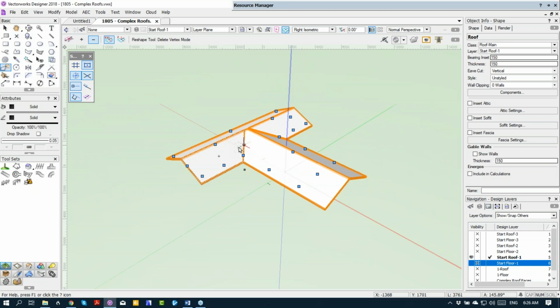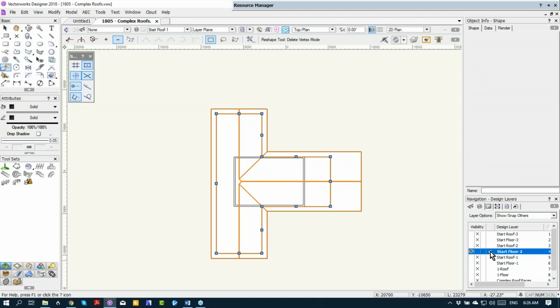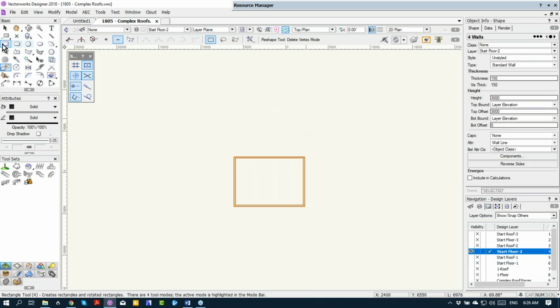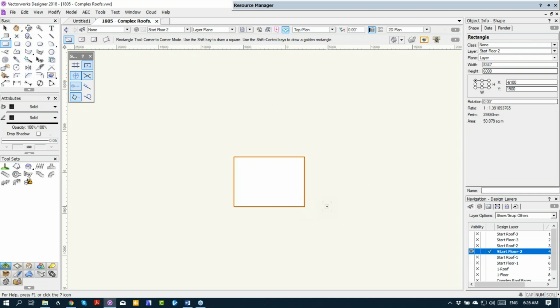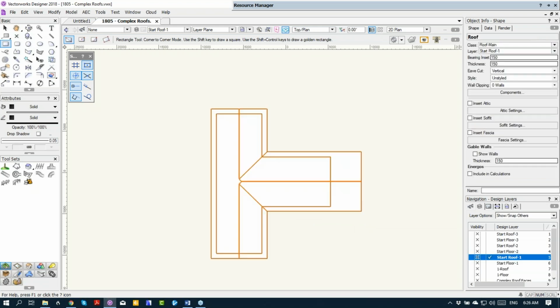So someone was asking about a mansard roof. So what we'd have to do is to create two different roof parts. And what we want to do is to be able to cut a big hole in this roof. And the way that I would do that would be to have a look at floor 2, which has got an upstairs. I'm going to create a rectangle from there to there. So that wants to be my rectangle. This is going to become a hole. Let's cut that.